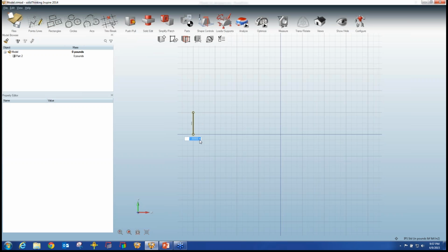And when I'm doing that, a cool feature is I could actually say I want this to be 5.08 centimeters, and I press enter, and it automatically converts it into inches. So if you've got your plans already laid out in another unit system, no problem. You just type in the units that you already know, and you can still create a sketch in another system of units. So I'm just going to Control Z again.